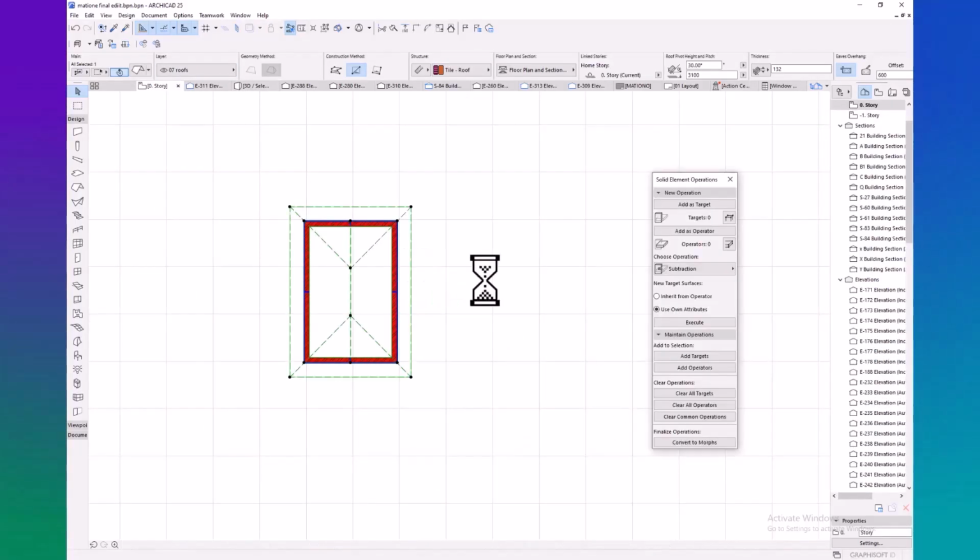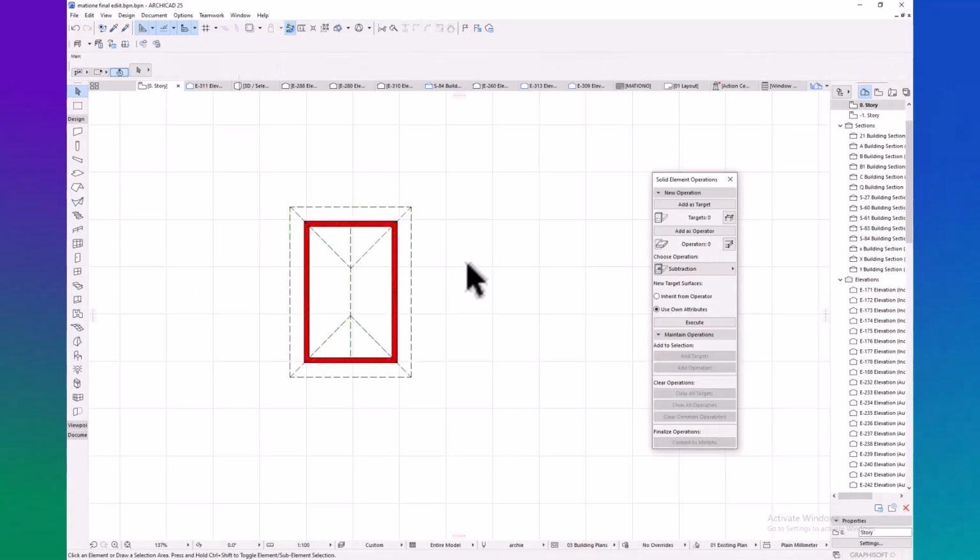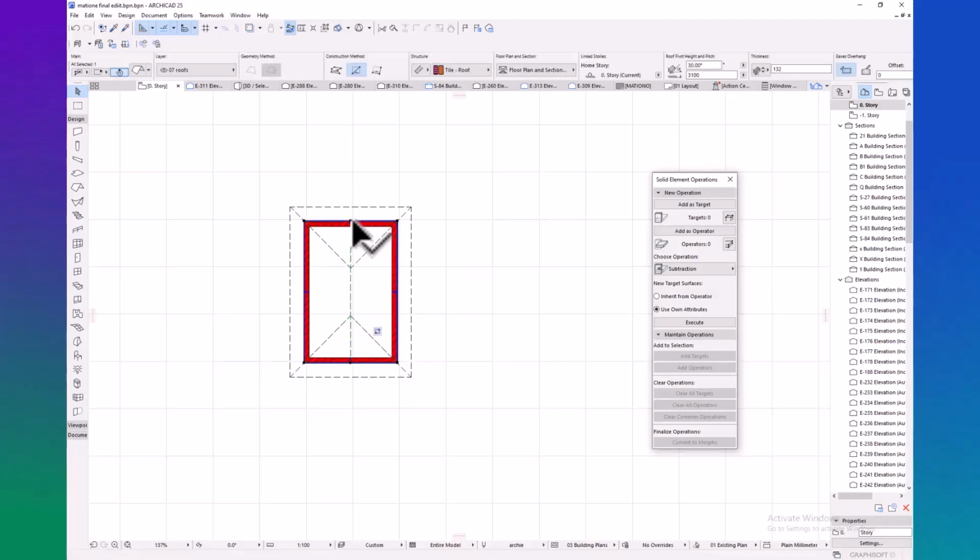our 2D plane now. We come and select the Dutch gable again. We click over the blue line, and the dialog panel appears again, and this time we select offset edge. Right. This is the size of the gable, so enter 1,000 on both sides. One side enter 1,000, go back to the other side.